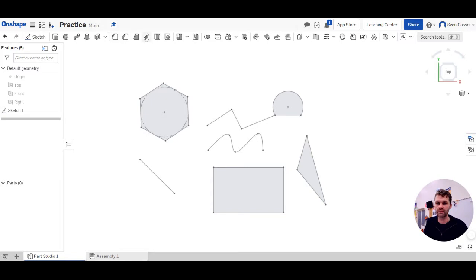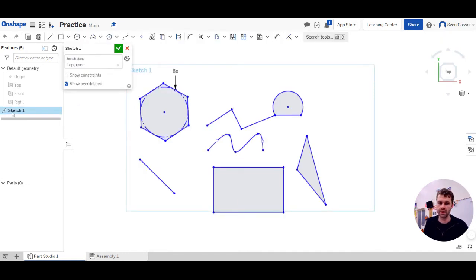You'll notice right now I'm in 3D mode, right? This is a common problem. People want to get back and start changing things. And right now you can't change anything here. You've got to reopen this sketch by double clicking on it. Right there, and now I can start moving things around again.